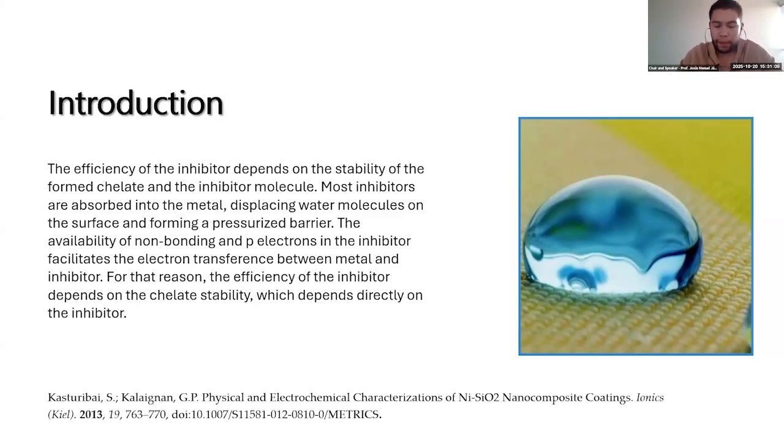When we apply a super hydrophobic coating, we are looking to make a self-cleaning system, where the drop of electrolyte can be displaced to another part to reduce the corrosion. For that reason, we are applying this type of super inhibitor. The aluminum alloy is employed because it is widely used in the aeronautical and automotive industry.